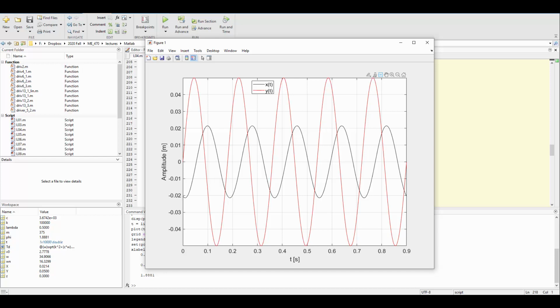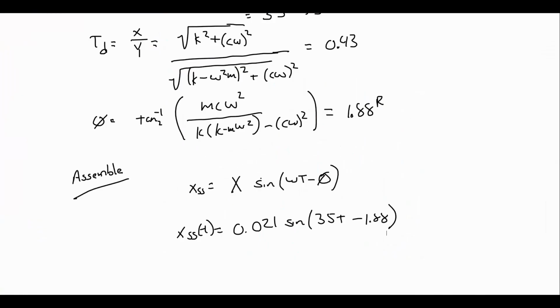So we see again the tires are going to go from the baseline up by 0.05 meters and then down from that baseline by 0.05 meters, and up and down, and that's that repeating pattern of the washboard road. And we see the cabin is experiencing about half of that. Well, we already knew the transmissibility was 43%, so it's 43% as much displacement while we're riding in the car as what the tires are experiencing on the road itself. So that addressed the first part.